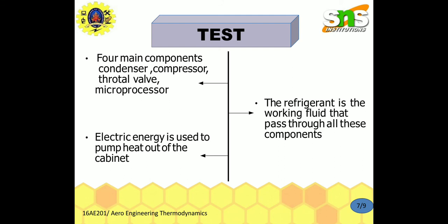In the gas cycle, the refrigeration effect is equal to the product of the specific heat of the gas and the rise in temperature of the gas on the low temperature side. Therefore, for the same cooling load, gas refrigeration cycle machines require a larger mass flow rate, which in turn increases their size. Because of their lower efficiency and larger bulk, air cycle coolers are not often applied in terrestrial refrigeration.